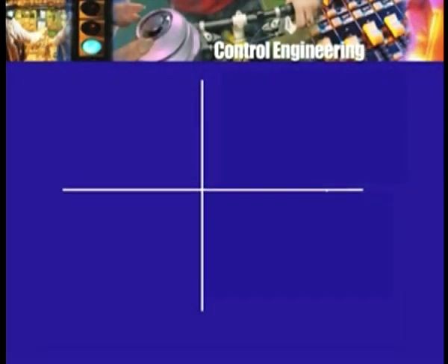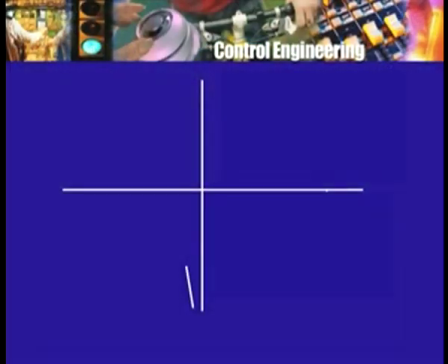As a result, at very low frequencies, the polar plot is going to start off something like this. This indicates a large value of gain and a phase shift which is very nearly 90 degrees. Of course, I cannot draw a very big diagram here, so you have to imagine that this is really going towards the negative imaginary axis side. So, it starts off from here at low frequencies. At high frequencies, the phase shift is minus 3 pi by 2, the gain is virtually 0.